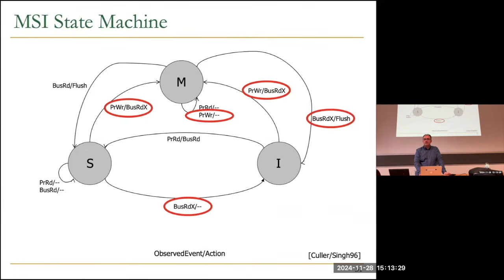Is there a logical reason why it is bus read exclusive instead of bus write? No, this is just, I guess, naming. It's a kind of terminology, and if you check different books and papers, you're going to see a lot of different terminologies. But the reason is that you want to read this. I agree, actually, you want to write it. That's true. But it is exclusive because your access is going to be exclusive. You want to update.